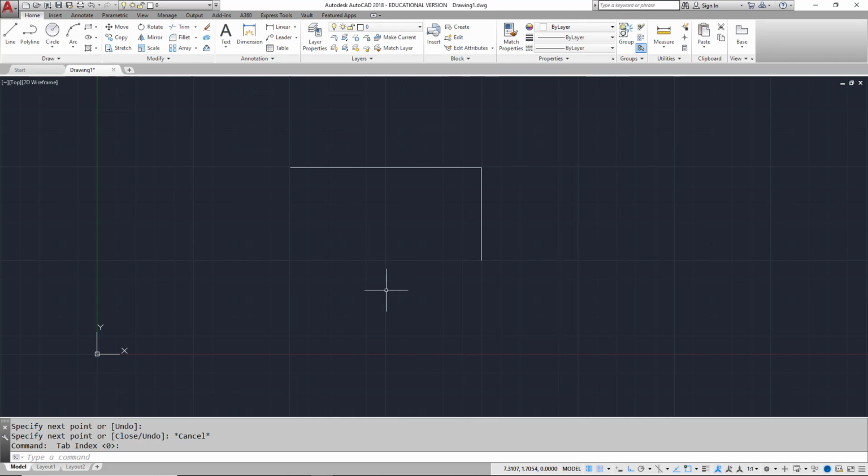And it doesn't actually become effective until I decide that I want to draw something. So I'm going to go ahead and erase these real quick. Enter. Now when I come in here and I say I want to draw a line, notice that my mouse only moves now to the grid. And my mouse only moves to the grid because of the way that I have that set up. My grid spacing and my snap spacing are exactly the same.